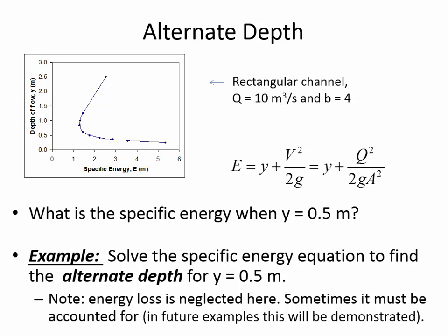So what do we call the depth when you have uniform flow and steady conditions? Do you remember that? Close. Normal. Very good. Okay, so normal depth. Normal depth just means normal conditions. There's nothing out of the ordinary. It's in equilibrium with the channel resistance, with the slope. Just everything's in equilibrium and everything's normal. You've got the normal depth.